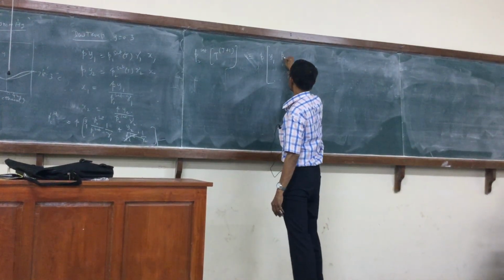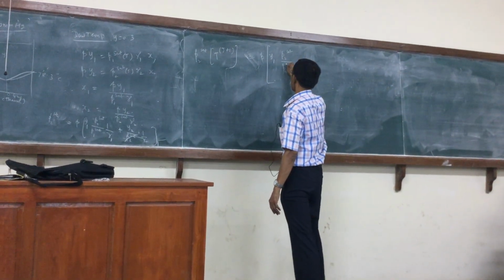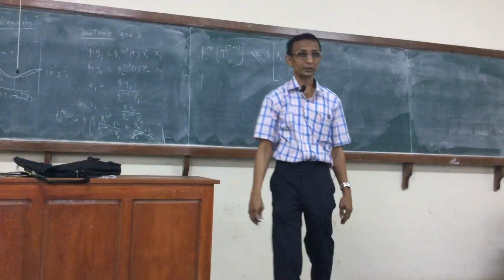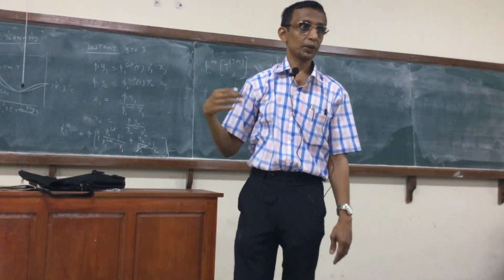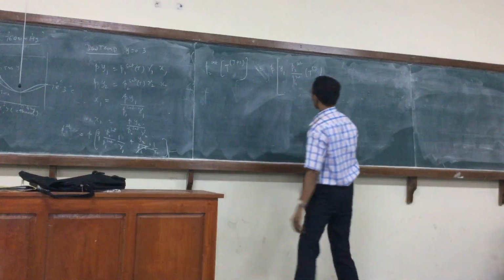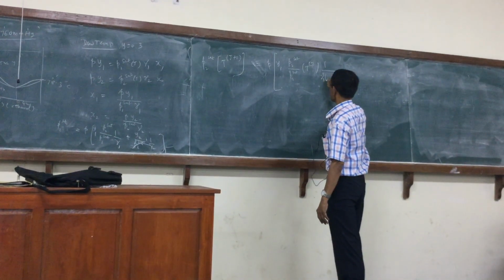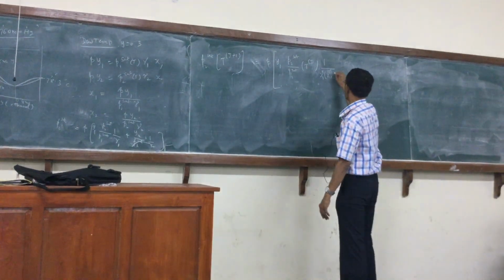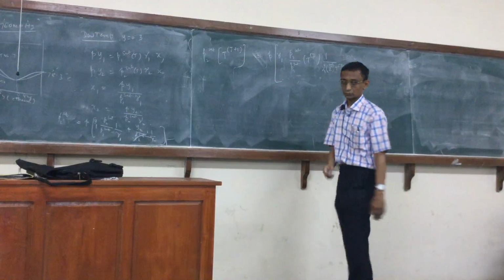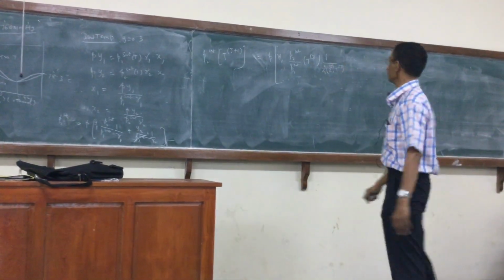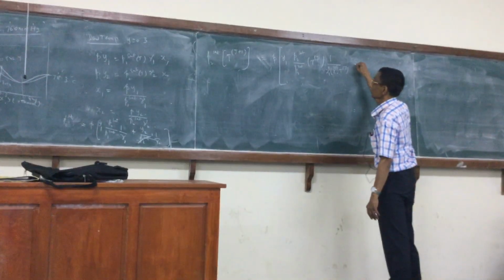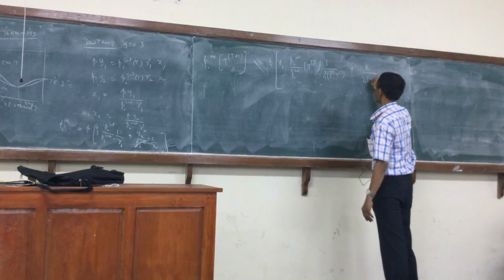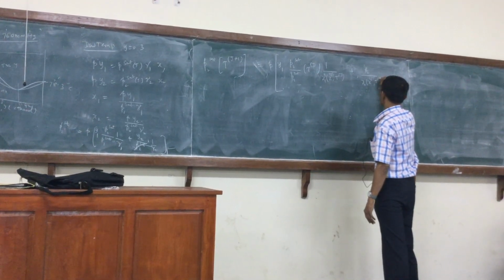So those are known quantities, right? And so P2 sat by P1 sat, this is now going to be a function of temperature, and I have to estimate it at a certain temperature. That would be the previously assumed temperature. And also, gamma1 would have to be also evaluated at an assumed value of both x and T, plus, and then I have y2 by gamma2 of x, T at iteration k.